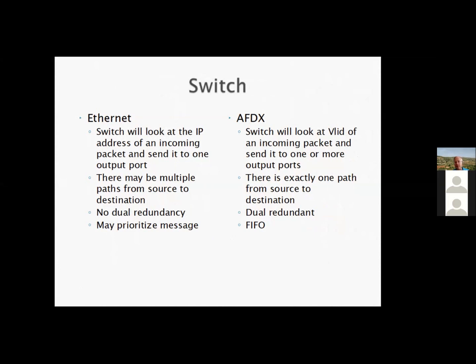Whereas an AFDX may send it out to multiple output ports, because it's going to multiple devices. Now, in Ethernet, as we described before, there could be many ways to get from a source to a destination, because each switch can choose among 10 different output ports that it's allowed to use to get to that particular destination. That doesn't happen in AFDX. In AFDX, the switches are defined so that there's only one way to get from any source to any destination.